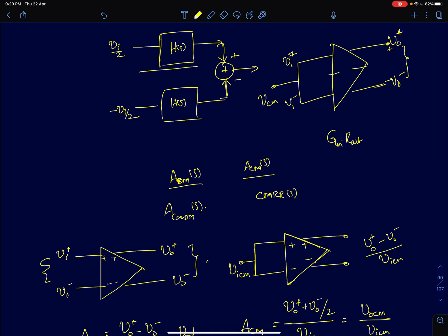We saw how amplifiers start losing their amplifying abilities and turn into passive circuits. In the case of a common drain amplifier, an ideal amplifier should be able to give a good power gain, but we saw how it loses its ability to give a power gain at very high frequencies because of the parasitic capacitors. Now naturally the next step in our analysis is to understand the frequency response of differential amplifiers.